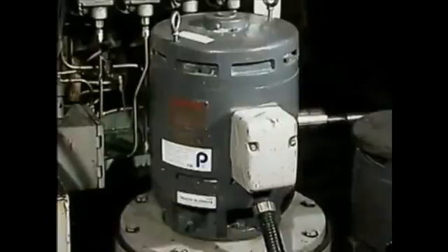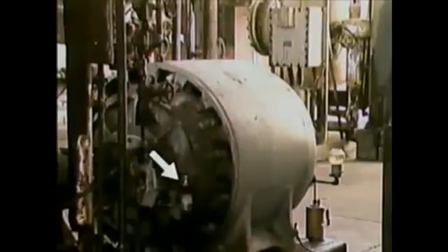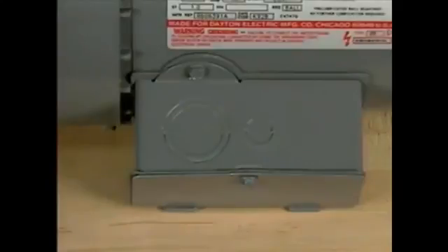There are some motors that use sealed bearings that do not have to be relubricated for the life of the motor. The bearings of some other motors are greased through grease fittings as part of a regular maintenance schedule. Other motors use a constant level oiler. A constant level oiler holds a small supply of oil that drains by gravity into the bearing. The design of the constant level oiler allows the operator to look at the level in the reservoir and add more oil when necessary. A connection box on this motor protects the motor's wires or leads from damage. These wires electrically connect the motor to a source of AC power.